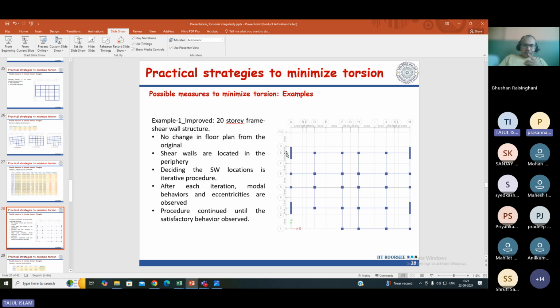No, this is actually just an example. The grid was already placed here, so I plotted it here. It's not like in the actual structure you'll have it like that. In the actual structure, what you can do is provide an L shape at the corner. That is one way to do it. Either you provide an L shape, or you just bring it inside so that your external edge is located at the corner. You can do that also.